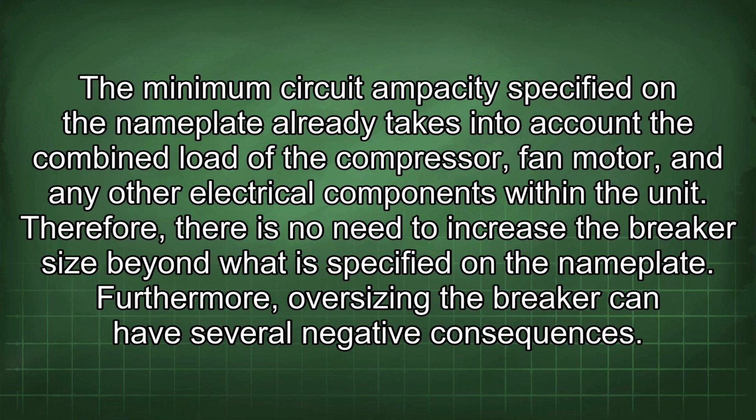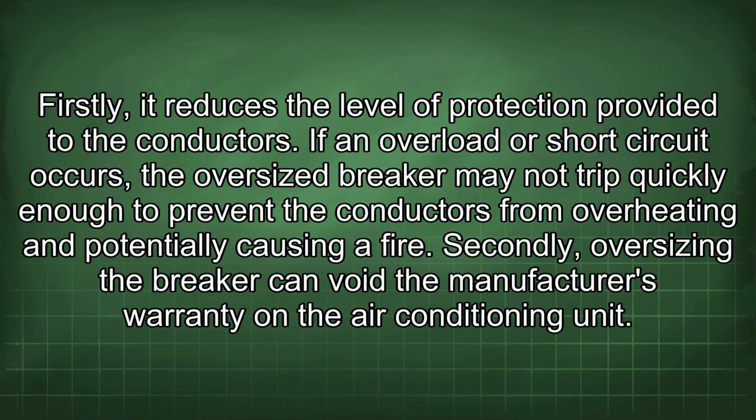Furthermore, oversizing the breaker can have several negative consequences. Firstly, it reduces the level of protection provided to the conductors. If an overload or short circuit occurs, the oversized breaker may not trip quickly enough to prevent the conductors from overheating and potentially causing a fire.